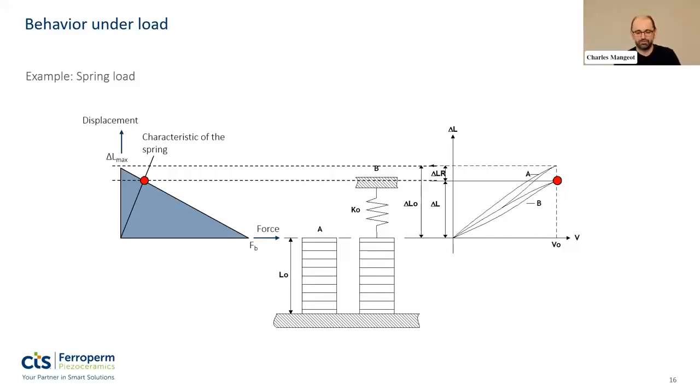Right, so basically the actuator can provide either the free displacement, so a change in position equivalent to the free displacement, or the blocking force if it's completely blocked, or a combination. So in many cases, it will be a combination, so you will need some force, and you won't get the full free displacement. And this is why it's very important to characterize your load precisely, because you need to make sure that you will be able to move your load by the amount that you require.